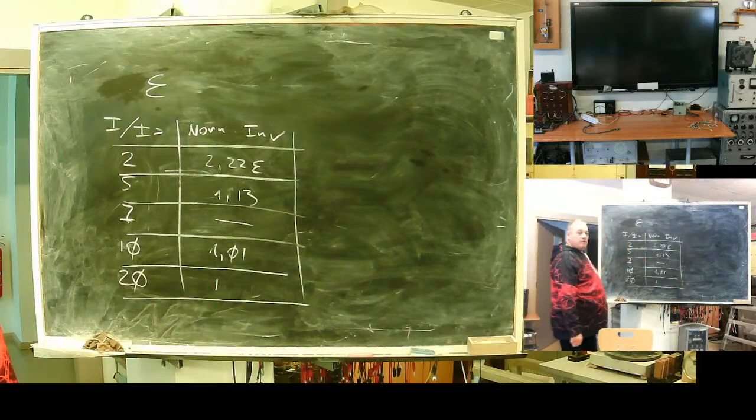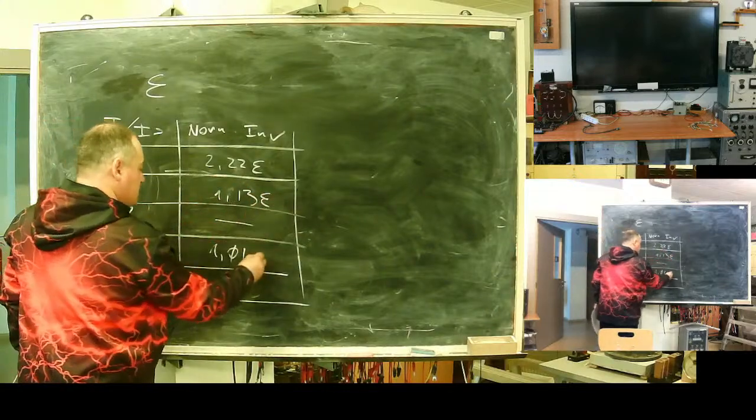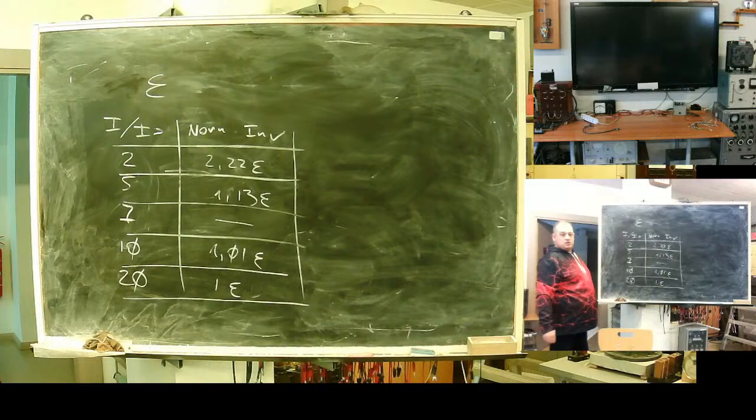You see? The standard allows lower tolerance at a small current. So be careful to provide sufficient margin if you coordinate two relays.